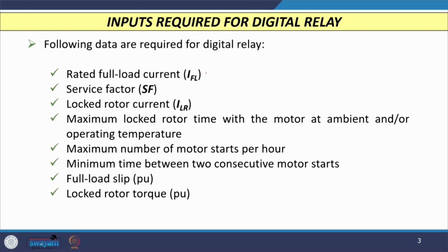The first input required is the rated full load current of the induction motor, normally denoted by I full load. Then you have to input the service factor. We will discuss what the service factor is. It is basically the percentage of current above the full load current which the motor can withstand when normal voltages are available at the terminals of the induction motor.